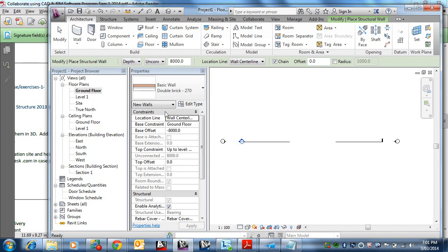All right, so what have we got here? Now when I click that, this here wasn't there before. This is your options bar. It's a bit like your command line in AutoCAD. You can set up different options for different commands. Windows will have different things to walls, for example. So always look here, always look in here. With Revit, it could be anywhere. The setting you want to set could be here, it could be here, or it could be in both places. Or it could be on a pop-up dialog box. So it's not uniform in the way it thinks as yet, but it's getting there.